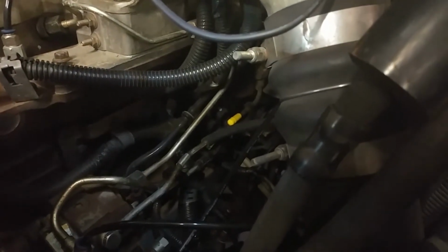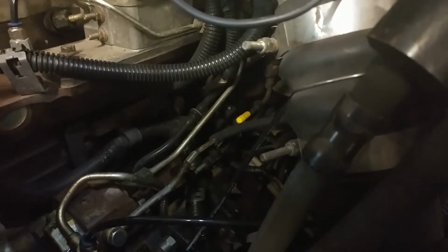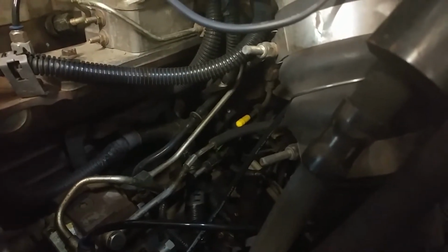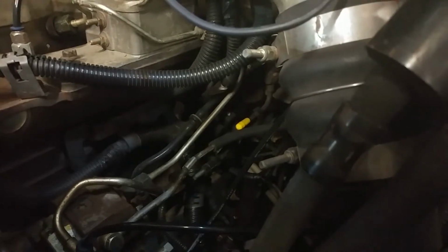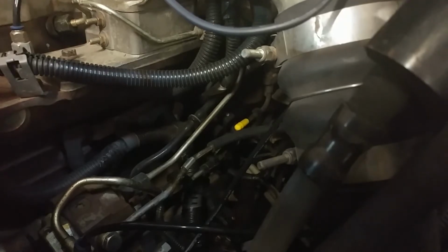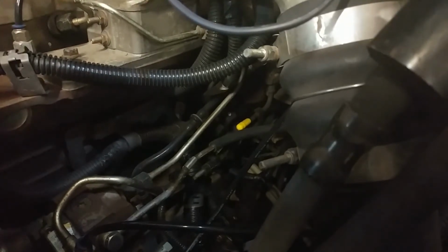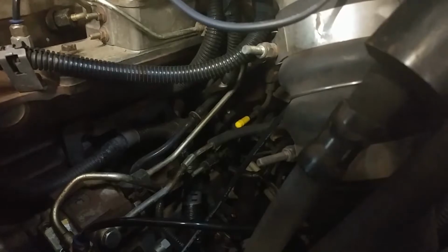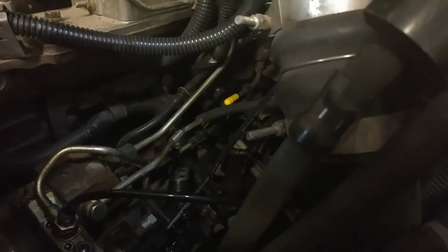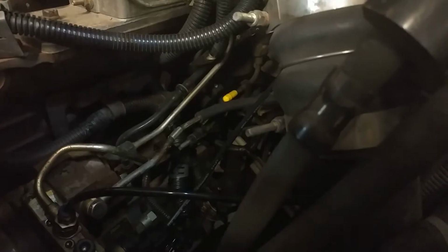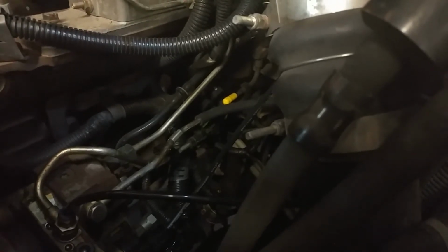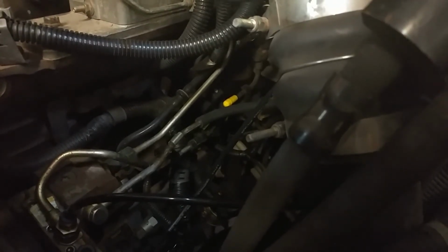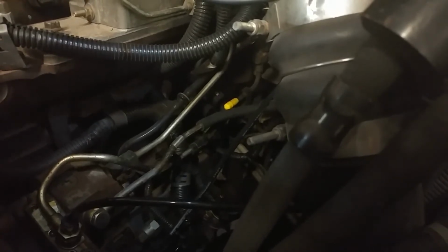So common rail means more than one thing. First, it means common rail as there's a single line from the pump up to the fuel rail, and all the injectors connect to this common rail. Well, the returns do the same thing. So to do any type of testing for individual components, we need to be able to separate these returns and measure these volumes independently. So that's what we're doing here. We've separated the CP3 pump from the rest of the system, and we've also got the injector return separated from the system, so we can independently measure these amounts.